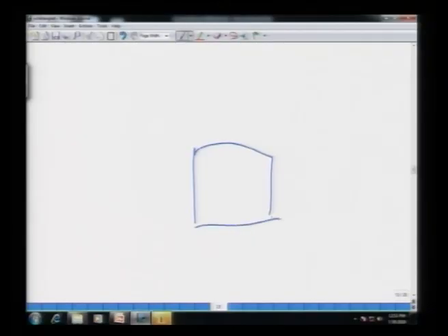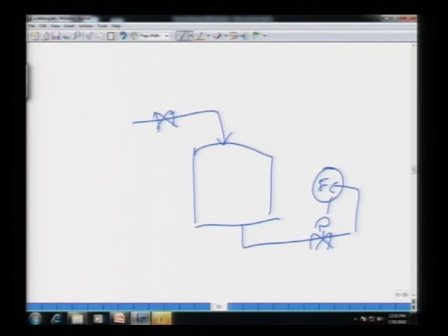If you take the reverse situation, and let me explain this here, the flow controller is here and the level controller is now on the feed. They are controlling the level this way. Okay. Now, if the set point here is increased, the flow out would increase, and the level would start to decrease. Now, in order to bring this level back up, what should I do to the inflow? Since the level is decreasing, I must increase the inflow. What that means is, if this valve is initially 50% open, it should be opened beyond 50%, to maybe 60, 65, 70% in order to bring the level back. So, what we are saying here is, if the level is increasing, controller output should be decreasing. Alternatively, if the level is decreasing, controller output should be increasing. This is called reverse action.